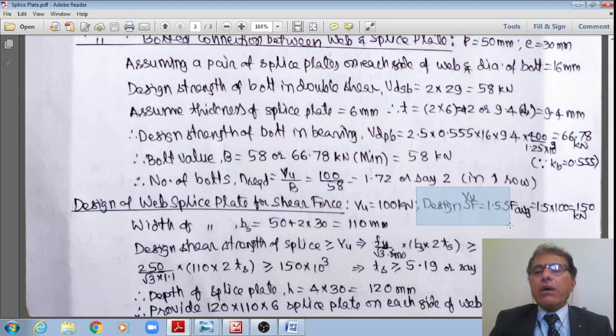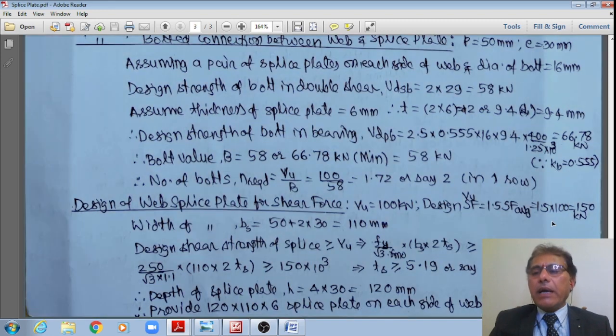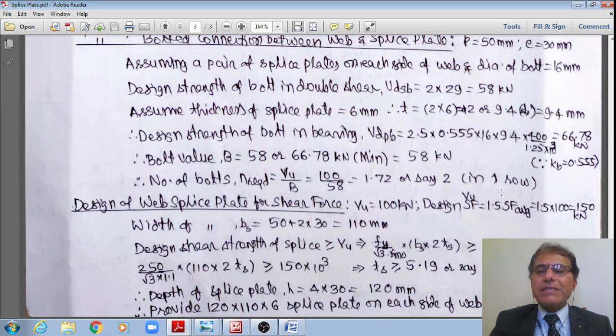Therefore, from that strength of materials variation of the shear force, I now say that the maximum design shear force is equal to 1.5 times the average shear force. Already the average shear force is the design shear, but at the central axis of the web of this column section, I am assuming 1.5 multiplied by that 100 kilonewton. Therefore, I am designing for 150 kilonewton, not just for 100.